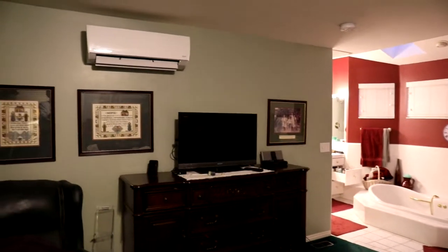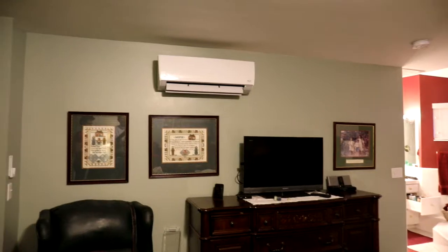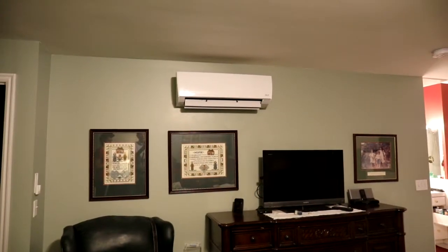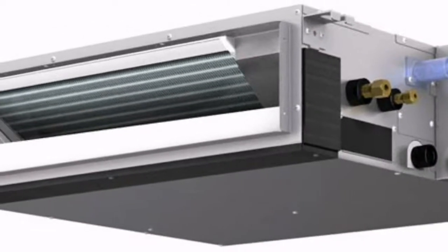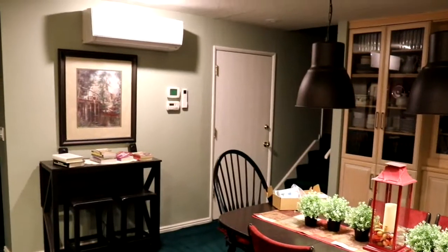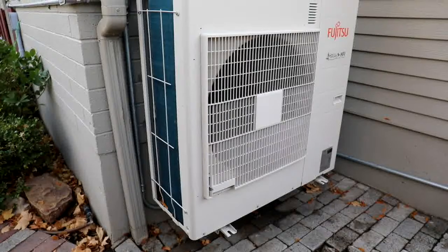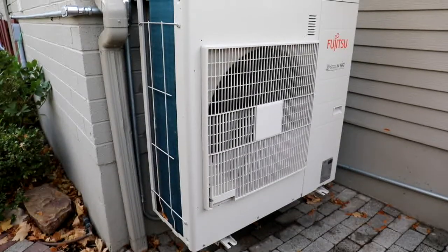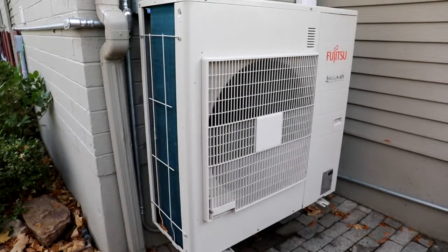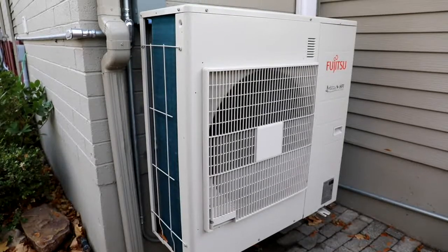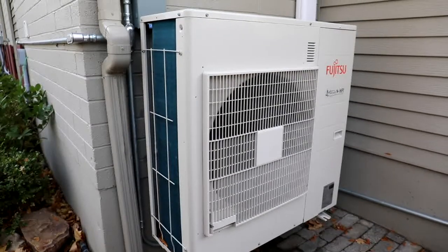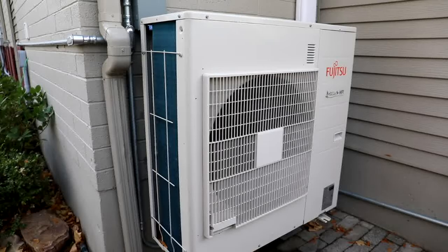Mini-splits are a unique class of HVAC equipment allowing both heating and cooling through a single room head. The heads can be mounted inside the ceiling, on the wall, or at the baseboard. The outside unit can service anywhere from 1 to 8 heads, but only single-room mini-splits allow for simultaneous room-by-room heating and cooling separate from all other zones.